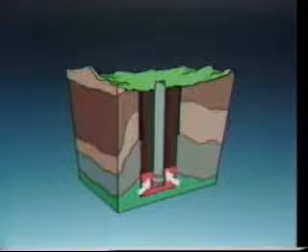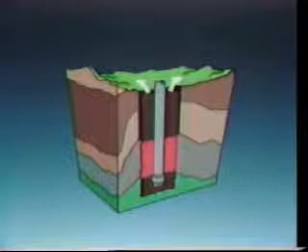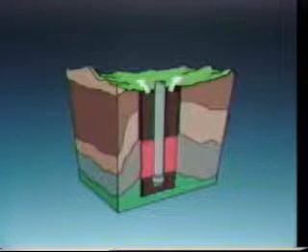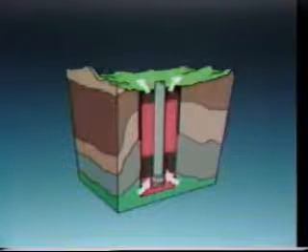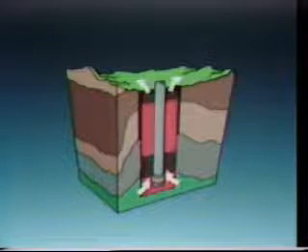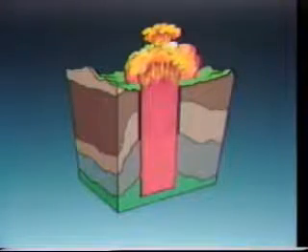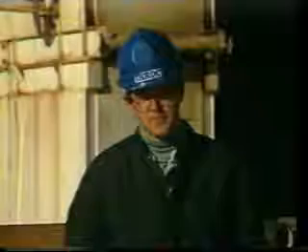As it pushes the mud out, the pressure exerted by the mud column on the bubble decreases, allowing the bubble of gas to expand and push more mud out of the hole, which can allow more formation fluid to enter the wellbore, which can lead to a blowout.